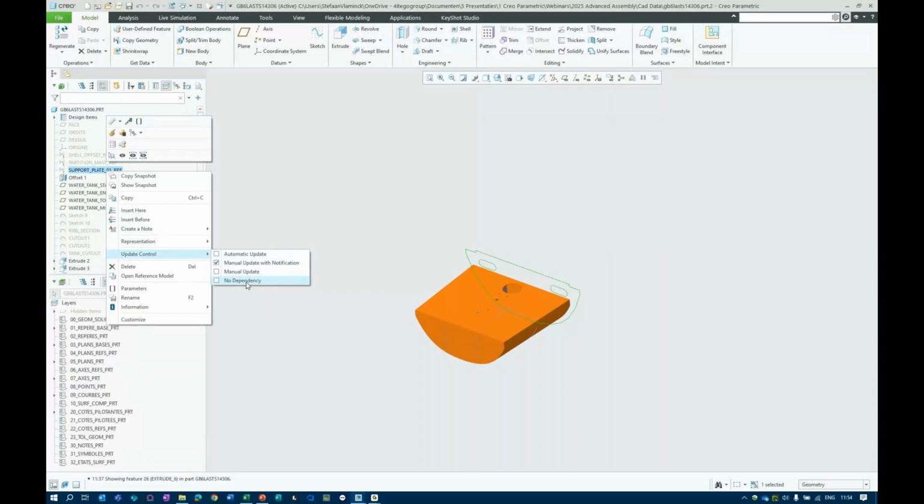Hereby you break the link. And yes, it can be restored, but not that easily. Broken is broken, and we use that in another assembly. So it's not linked to this assembly anymore, but that means that the geometry that is imported, I cannot change as well. So it's a little bit in between.